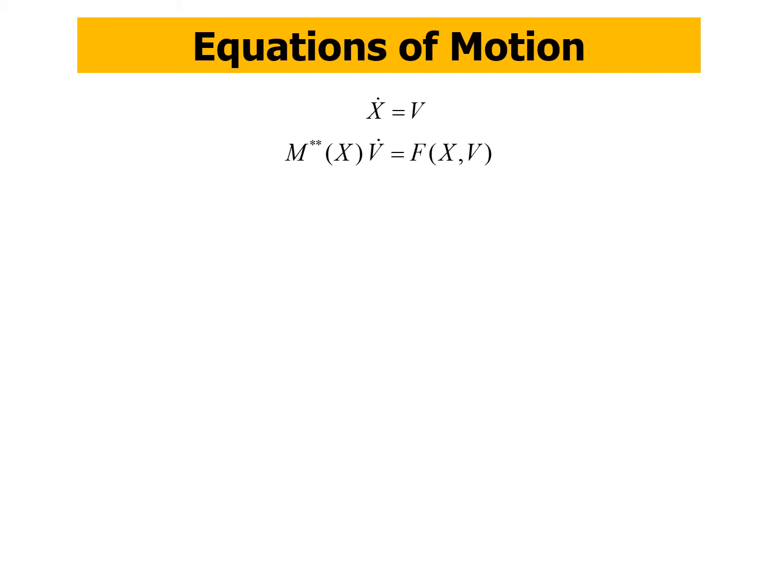X is only position. So this big M here is actually the relation matrix transpose with a diagonal mass matrix, M D, and then we have the relation matrix, not transposed. The transpose is moving the columns to be rows and the rows to be columns. The relation matrix, we get it from the idealization, how the segments are connected and where the masses and the lengths are.